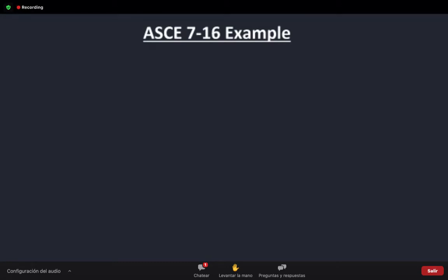Now, to get the width of my L shape, to see how wide my L shape is going to be, does anybody know the equation for that? What am I going to multiply? Come on, Greg, you're on a roll. 0.2. 0.2 times the building height. Awesome. So, Chino, the building height. What about the building width?